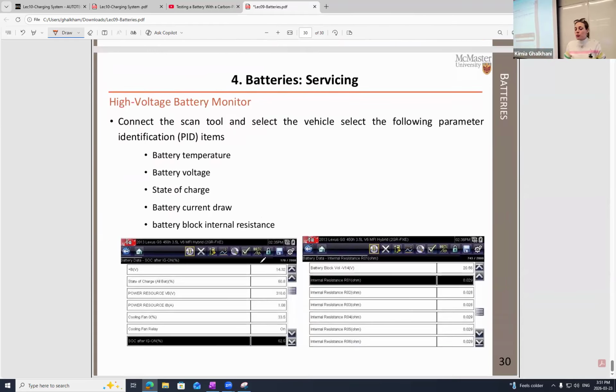Very last slide in here before I finish it and move to the next topic is going to be about the scan tool. A scan tool nowadays, we don't really use the scanning individually in case we have proper sensors to be connected and look at the functionality of the battery, the temperature, the SOC, the SOD, state of discharge, the SOH, state of health, and so on. Even resistance and everything could be nowadays monitored through the battery management system.